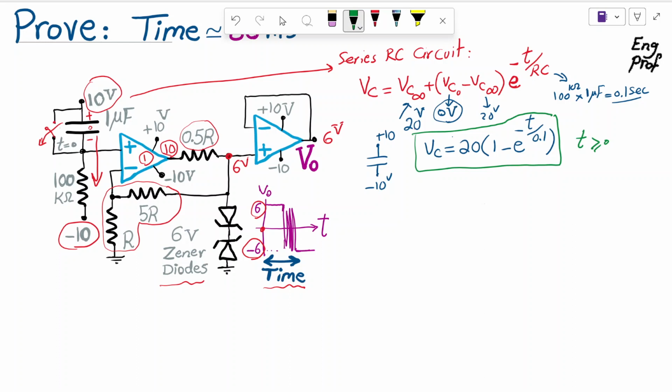Well, as the voltage of the cap, so let me put it back, what the resistor we have. So here is the resistor, and here is the negative 10 volt at the bottom of the resistor at the input of the system. As the voltage of the cap is increasing, voltage at this node is dropping. So initially the voltage at this node is 10, but then it starts going down as the voltage across the cap is increasing. So 10 becomes 9, becomes 8, 7, 6, 5, 4, up to plus 1.